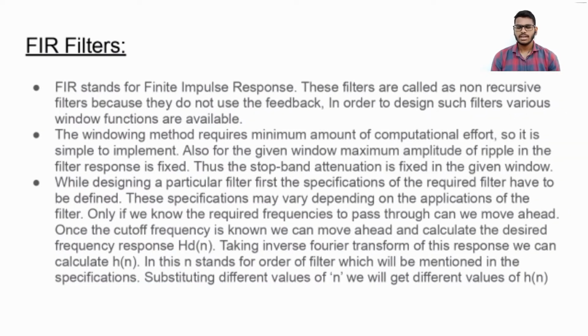This is FIR filters. FIR stands for finite impulse response. These filters are called non-recursive filters because they do not use feedback. In order to design such filters, various window functions are available. The windowing method requires minimum computational effort, so it is simple to implement. Also, for the given window, maximum amplitude of ripple in the filter response is fixed. Thus, the stop band attenuation is fixed in the given window.